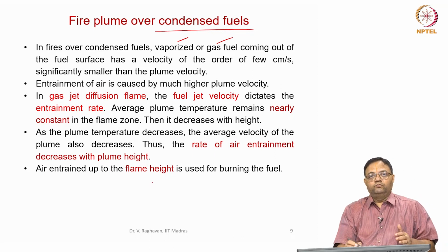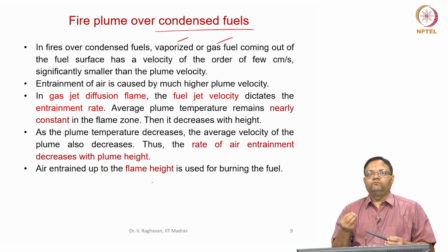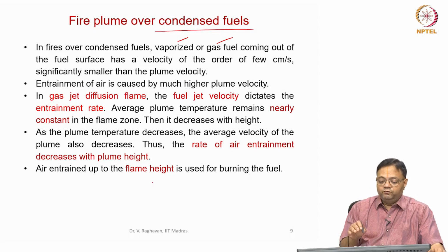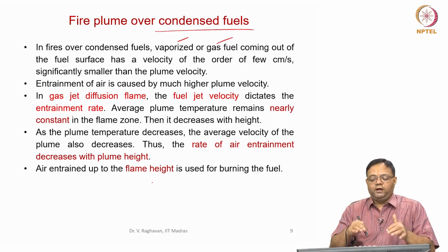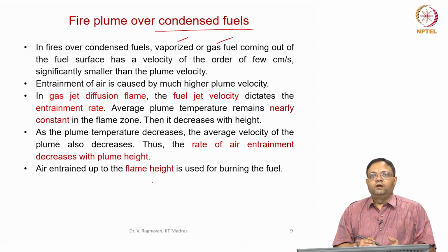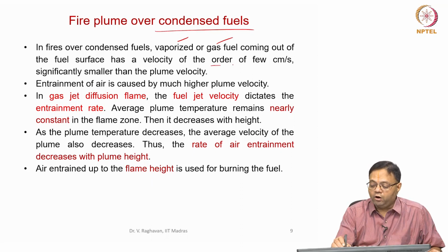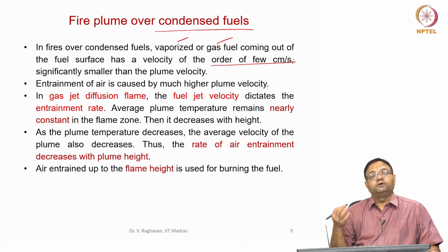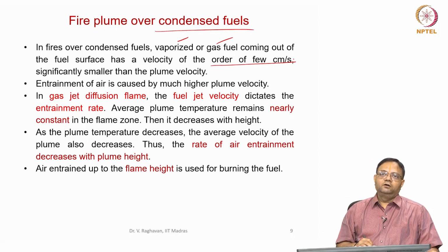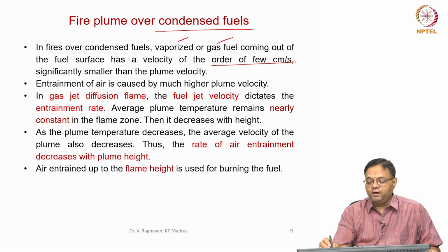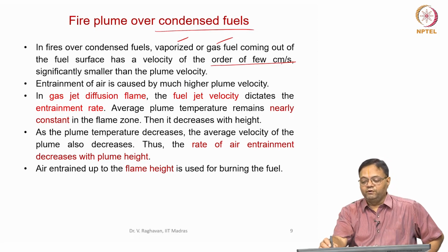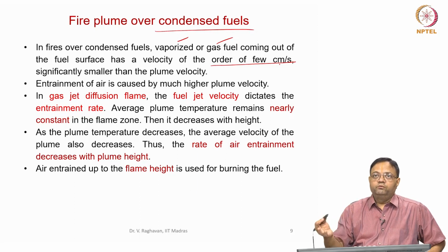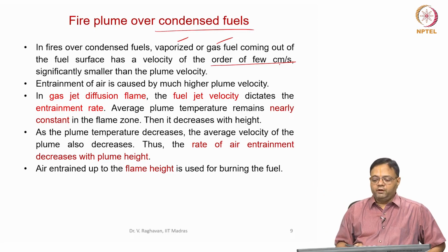This mass transfer will cause some blowing velocity or Stefan velocity, but this velocity at the interface, perpendicular to the fuel surface, will be very low, of the order of a few centimeters per second, say 1 or 0.5 centimeter per second. But the plume velocity itself will be much higher, maybe 5 or 10 or 20 centimeters per second.